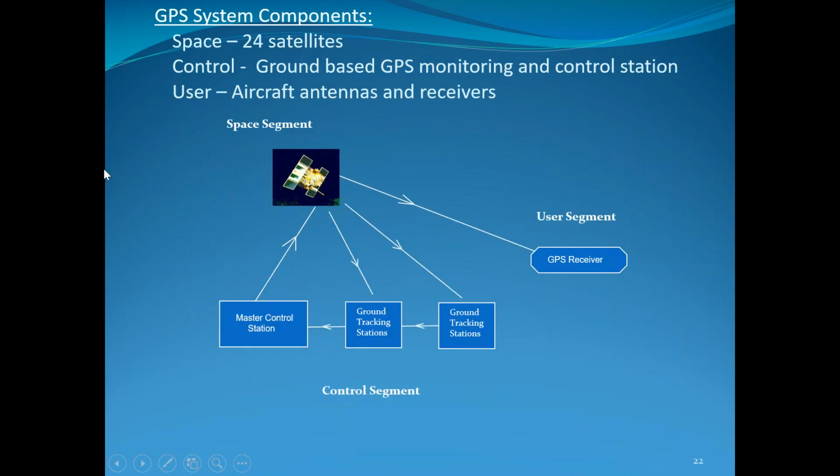This talks a little bit more about the GPS system here. 24 satellites, and I think there's actually more now, like 30 something. But you have to be able to pick up a certain amount of those at any given time. A normal GPS, like on your phone, I believe has to have 3 satellites in order to triangulate a position, minimum. Airplanes are required to have, I want to say it's 7 or more in view in order to double make sure and triple make sure that it is accurate.